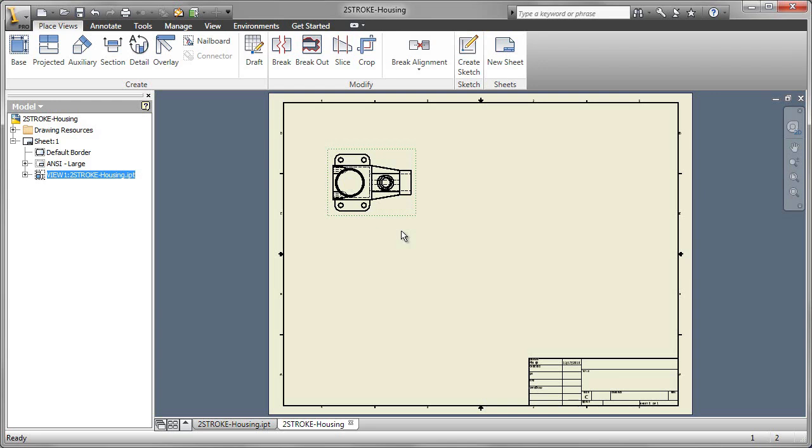When I select the orientation, none of these are acceptable. I want to be looking at the top view of the part. So I'm going to go out to the Change View Orientation tool, look at the top of the part, that's what I want, and then click Finish Custom View. Now I have the correct view in the drawing. And I'm just going to leave that top view and move it down a little bit.